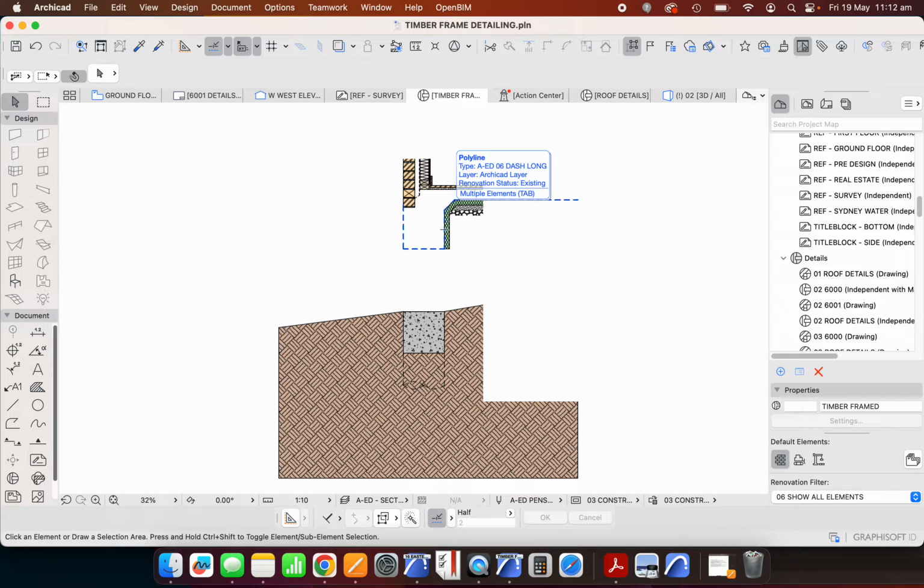And of course, the reality is that I don't want to have a chopped brick, so the position, I should say, of the ground to the building will actually be like this. And again, of course, it's the other way around. And so we'd be positioning the footing in the earth, wherever it needs to go, and then we'd be positioning bricks running up as necessary, and that would determine the heights of the other elements of the floor. Now, we don't necessarily need to have an exact relationship between the brick and the floor level, as we see here. This is dependent on a few other aspects that we're going to have a look at soon.